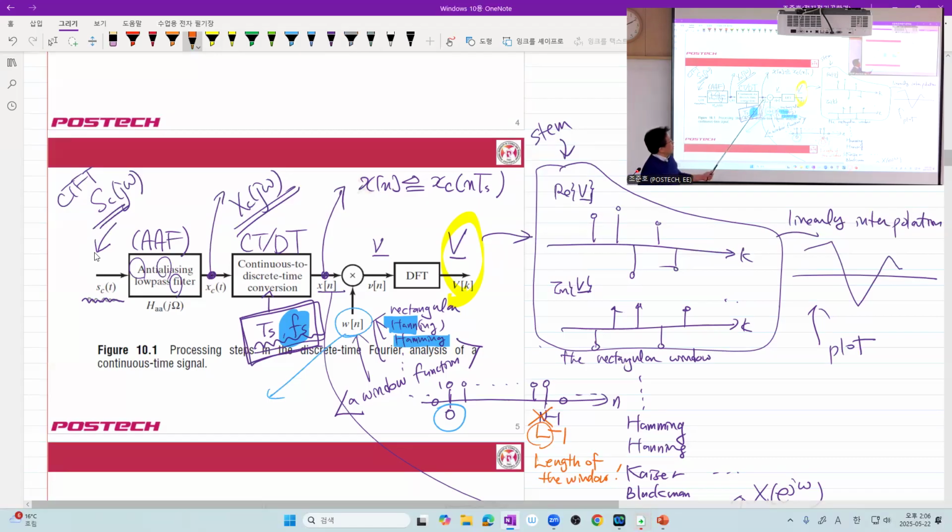And this length L signal with a lot of zeros now goes in. And here, if we choose N point DFT, it means we cut from 0 up to n minus 1 of this signal v, and then perform the N point DFT.